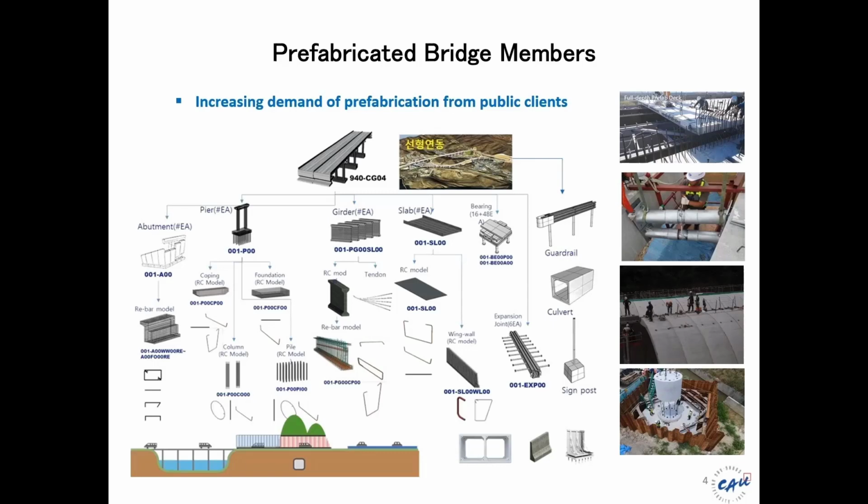But one thing we lack from those applications is the adjustment. I mean the pre-assembly, because they have different suppliers from different companies, and when they deliver their members to the site, the assemblers normally have some difficulty. So we need to digitalize the data of geometry change from design dimensions.